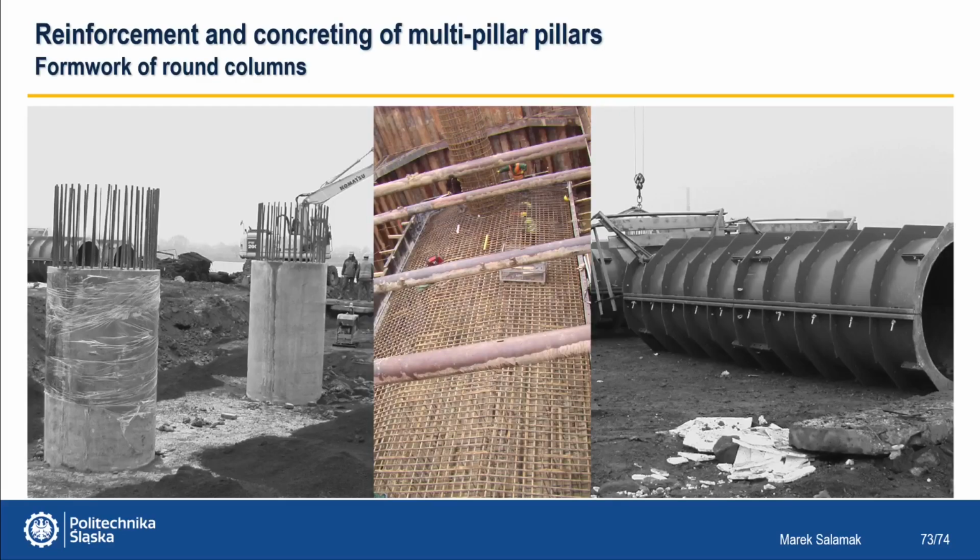After the reinforcement is laid in the pile cap, the column reinforcement is installed. The formwork for round columns is a special repeatable formwork. Concreting of high columns is staged and the reinforcement is continuous.